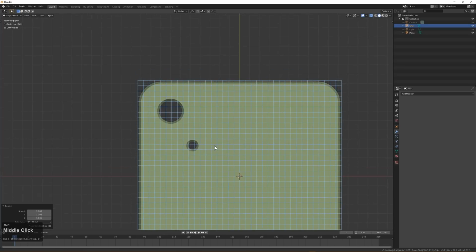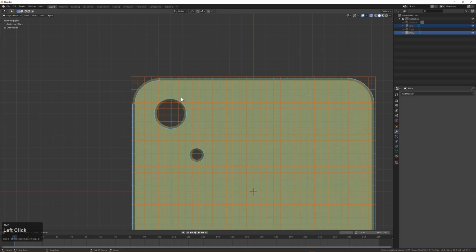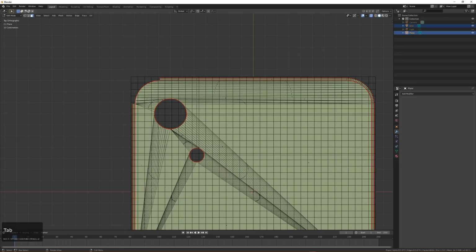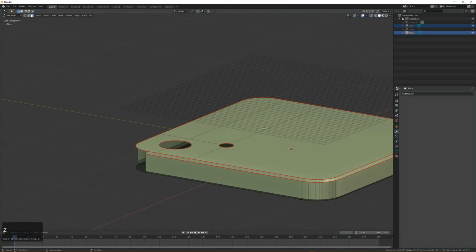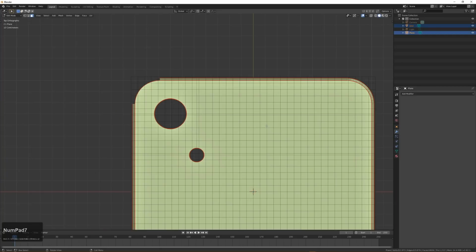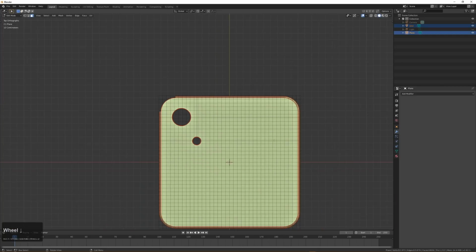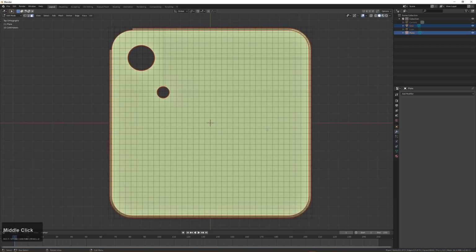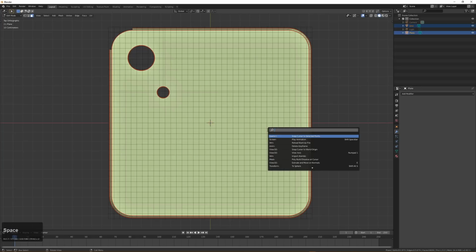And we have this mesh underneath. So we'll shift select the mesh underneath, tab in edit mode, maybe Alt Z to not see through it. That's what made me have to get out of top mode. And you remember I was talking about how spacebar is your friend for options that you just can't find? Well, spacebar, and we're going to type in knife project.